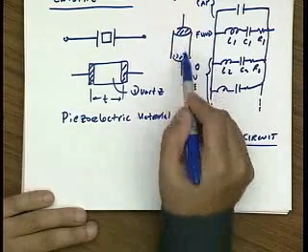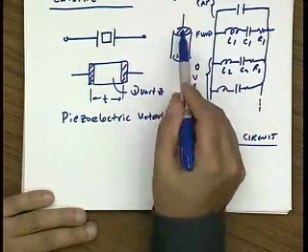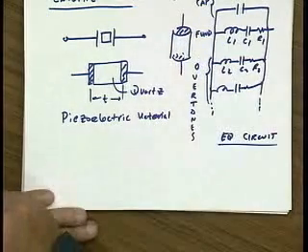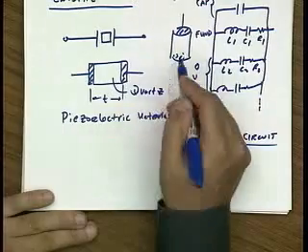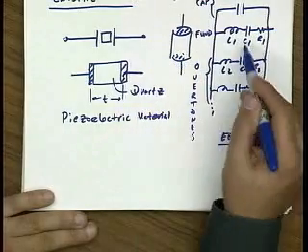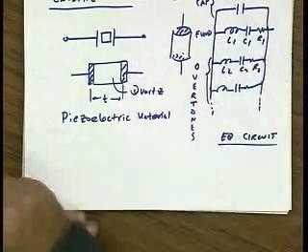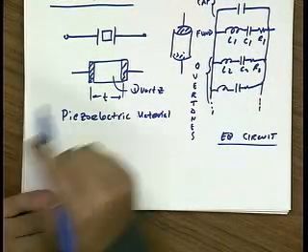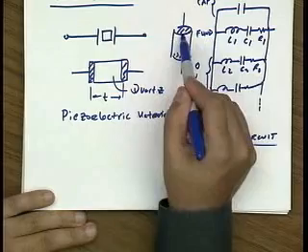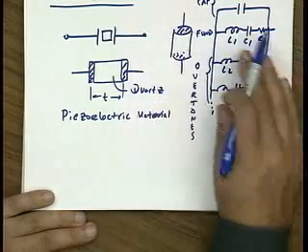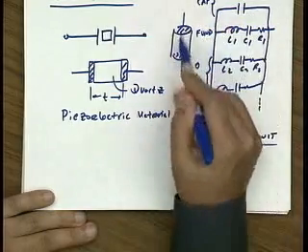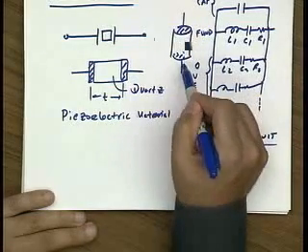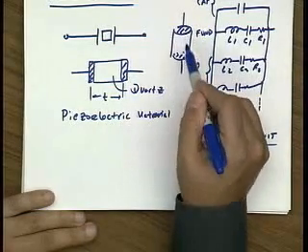The C0 is just this capacitance. You just have two terminals, right? This is a dielectric, and so it's basically a capacitor. If this were not a piezoelectric material, all these elements would go away. You just have a capacitor. In parallel, not series. Because it is in parallel, right? What you're doing is, forget about all this stuff, right? It's just a capacitor. And what happens in between is you induce waves that flow back and forth here.